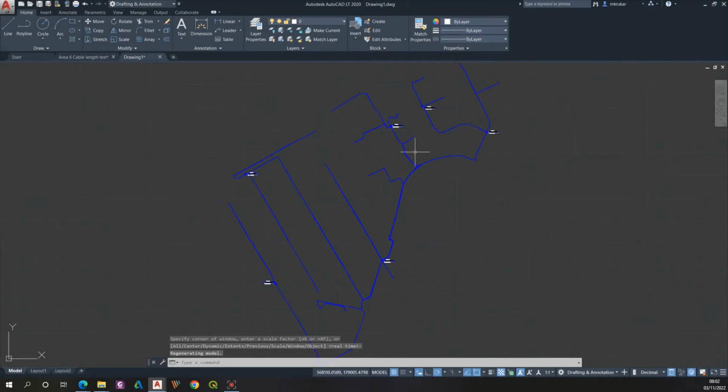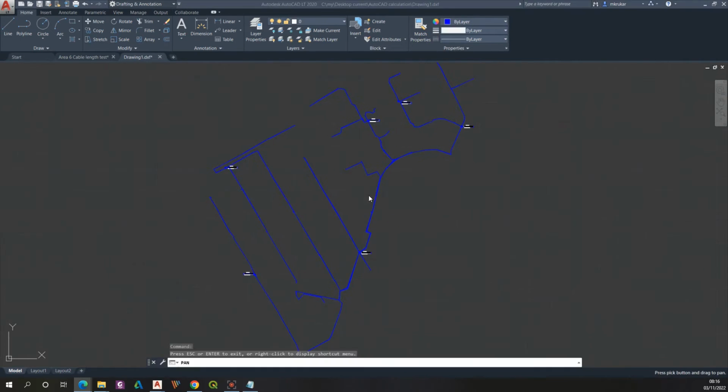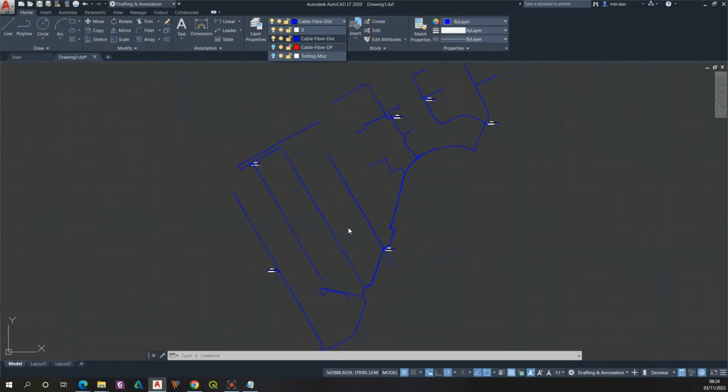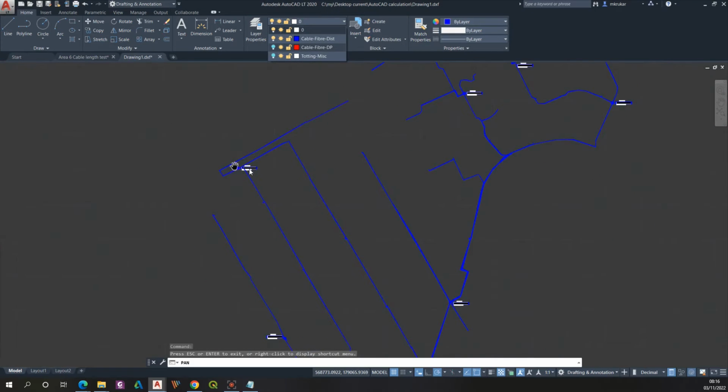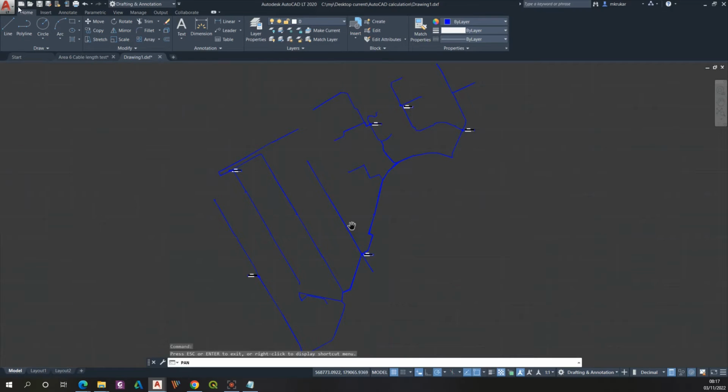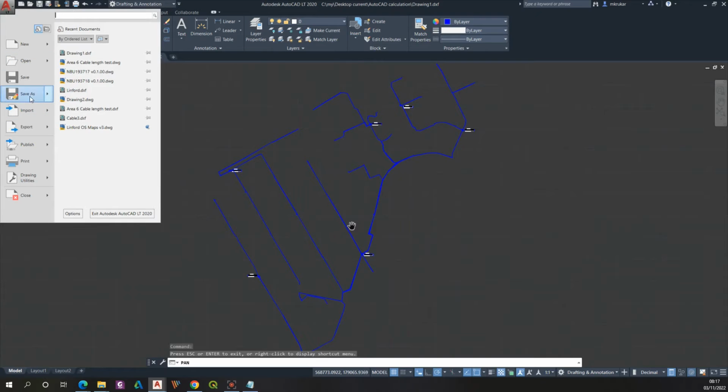All right, so that's fine for this moment. We have some layers available here. Let's check them, because by default layer 0 has been set. When I drop down this box, I see that I have 4 layers instead of just 1, whereas just 1 layer has been isolated. It's driven by the inherent parts which came with this layer, namely the labels, which you can see here, as well as some circular dots next to them. But it's not a problem. We can delete these layers in AutoCAD, but we can do it later, because what is most important here is that we need to save our drawing as a DXF file.